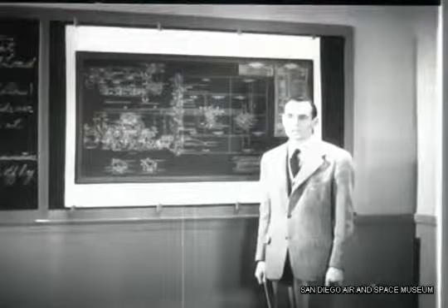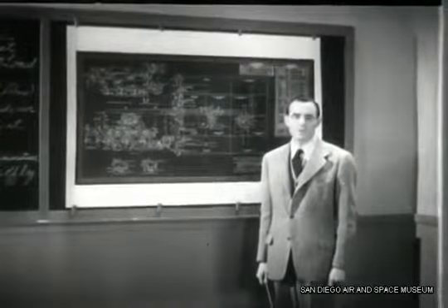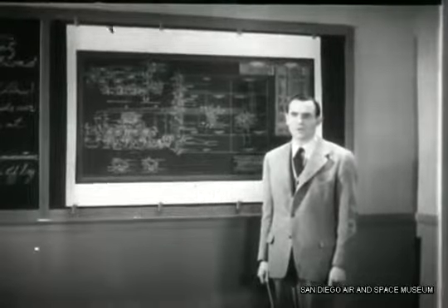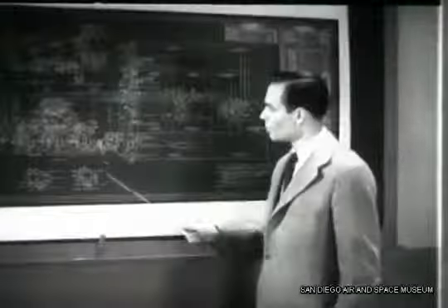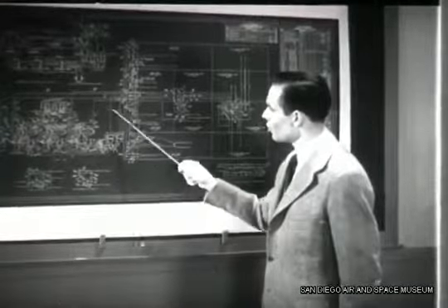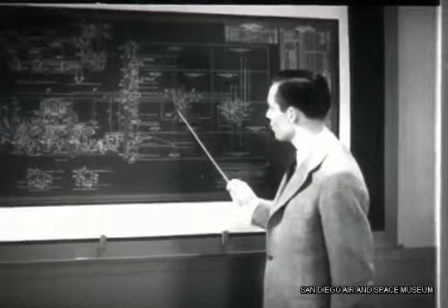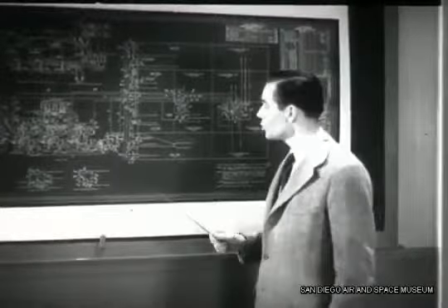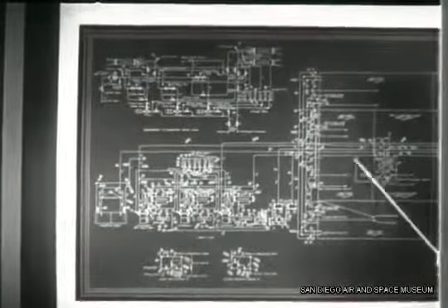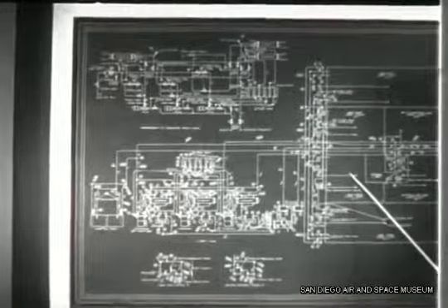Modern mechanical refrigeration is very simple. The theory is merely this. The liquid refrigerant, dichloro-difluoromethane, passes into the thermal expansion valve, breaking into small particles as it passes into the evaporator. Evaporation always takes place at the expense of total heat, or BTUs, of the surrounding cargo. Here, the rapidly moving molecules pass off as free gaseous particles.